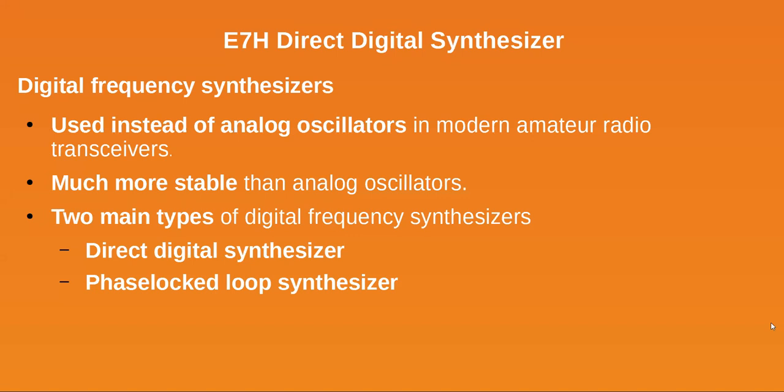Direct digital synthesizer. Now we're going to have a digital oscillator. They tend to be much more stable because they're typically generated from a crystal reference oscillator. You've got kind of 2 kinds, a direct digital or a phase lock loop.